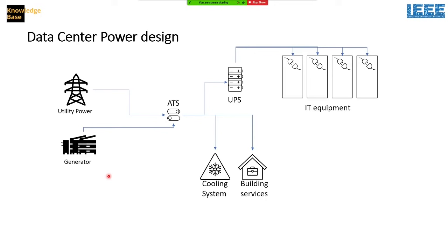So the UPS, and here I've seen this in my career, a lot of clients would come and ask, we need a UPS that would support our data center for 2 hours. You don't need it and you will never use it. The requirement and the recommendation by the standards is for 15 minutes. And this is more than enough, because in 15 minutes, your generator will turn on and start supplying power, and the UPS will be off. So in a data center, the UPS is only to support you during an interruption of power. The backup power is from a generator system, not from the UPS.